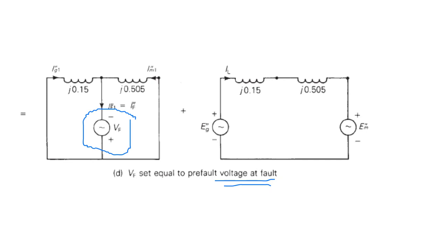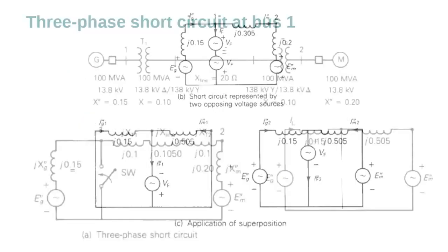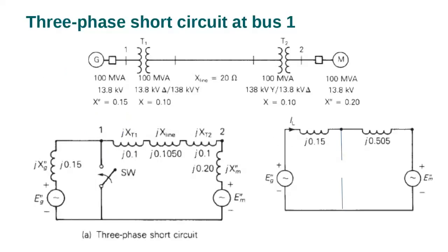Why? Because the current comes like this, down. And the current also comes this way, down. Remember, when a fault happens here, to ground, current flows from the machine all the way to ground. Now, the current flows from the machine, and also from the generator, to ground. The fault is like a sink. The water will come to the sink, and the water also will come to this.